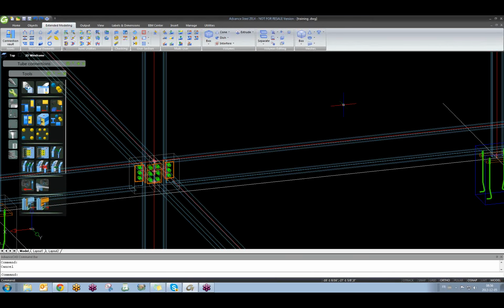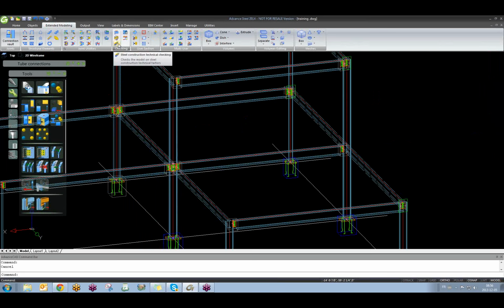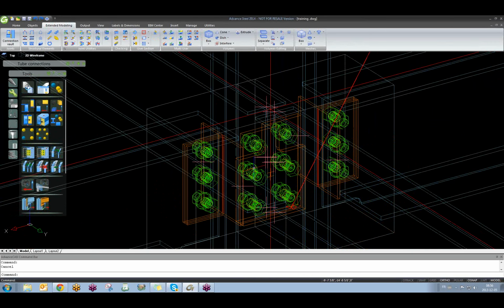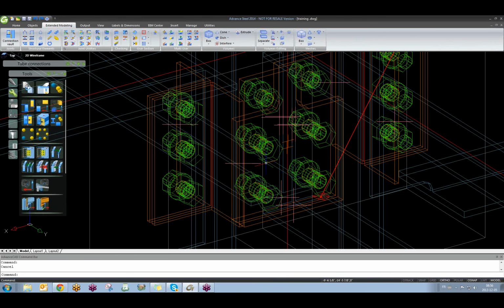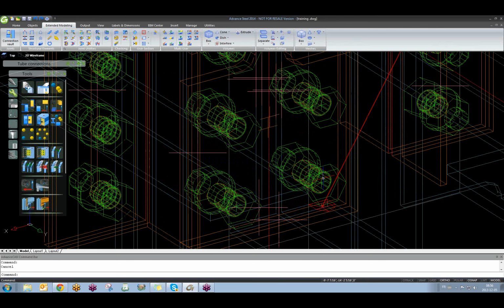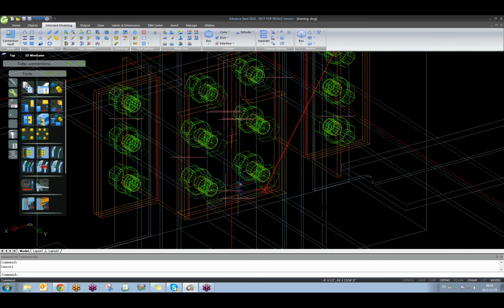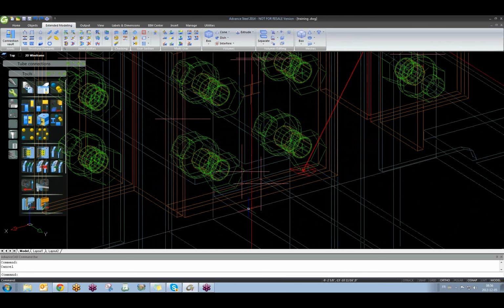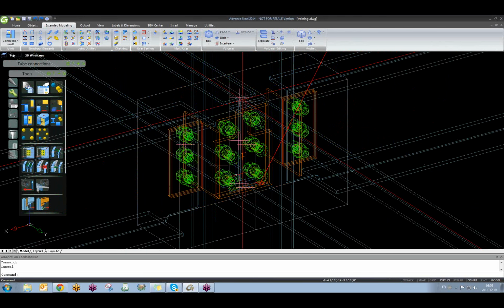Well, that was it. To fix that, you would go in and reduce the distance between your bolts to correct that error. Exactly. When you reduce the distance between the bolts in here, you will just have fewer clashes. That's it. Or you could cope the bottom of your beam. Exactly. You can do a cope in here. Cope that flange out.